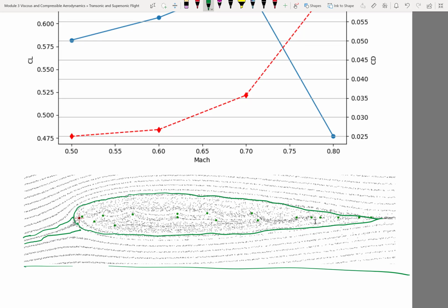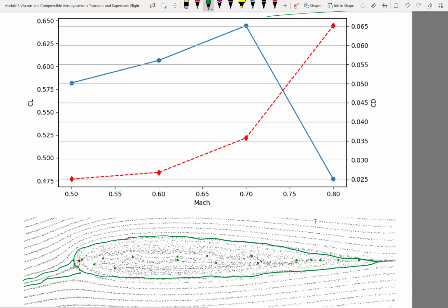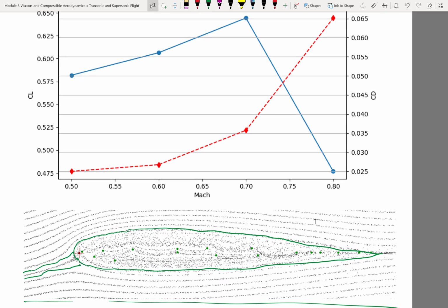Because the flow decelerates, the pressure has to increase, because that's what's driving the deceleration. So the question is, as you are decelerating in the incompressible flow field, the deceleration has exactly the effect of the area times velocity being a constant.